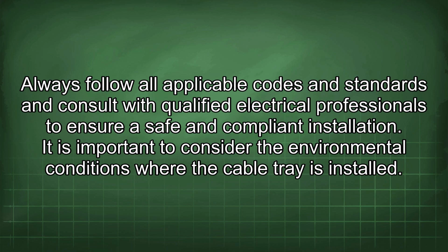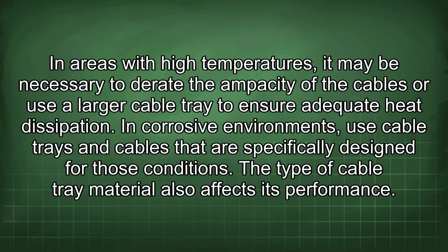It is important to consider the environmental conditions where the cable tray is installed. In areas with high temperatures, it may be necessary to derate the ampacity of the cables or use a larger cable tray to ensure adequate heat dissipation. In corrosive environments, use cable trays and cables that are specifically designed for those conditions.